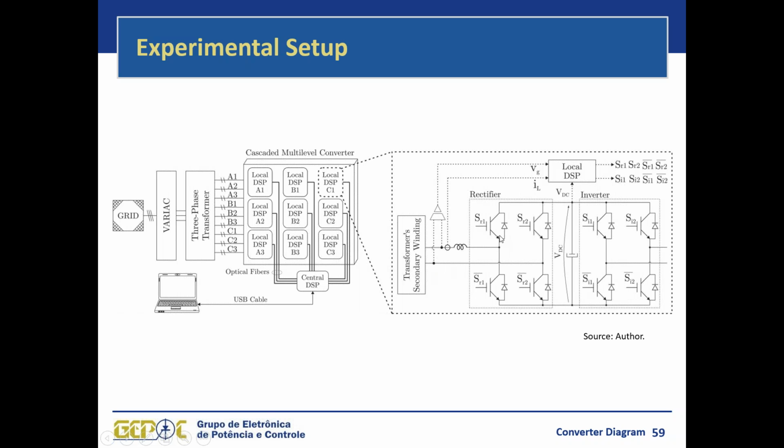So if you have diode rectification, you need to have those different phase angles for the input transformers in order to diminish the harmonic content of the input currents and so on. So this input transformer is very simple, which makes its cost very low, and it's easy to build because it's just a one-to-one transformer.